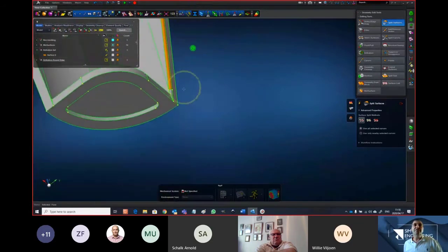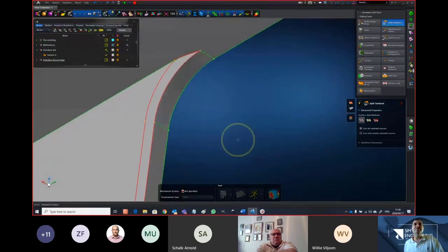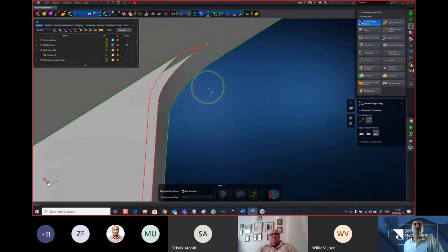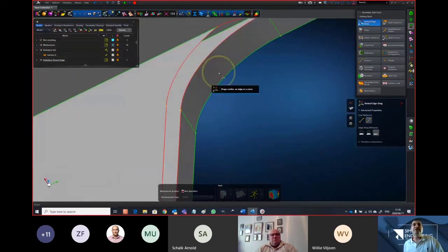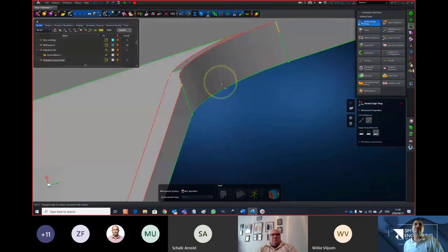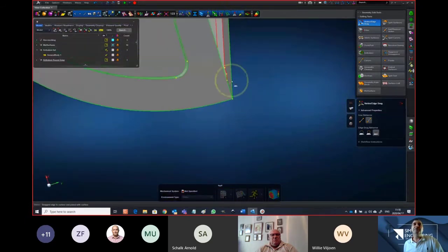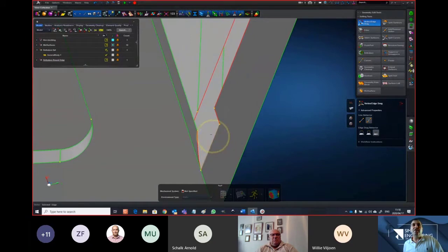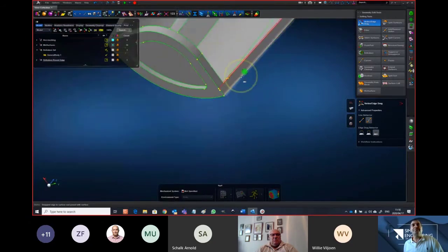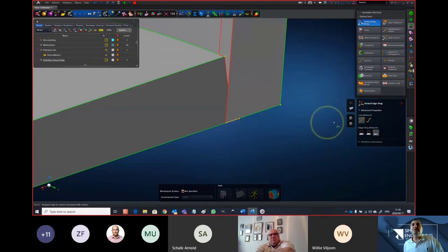Right, so I'll delete these two faces as well as a way to get rid of that feature because the defeaturing feature failed. And now I'll have access to all my sheet and surface feature tools, like for instance the ability to drag this edge to match up to the extension of that face over there. And now I just have to do this for these three edges, and then just take care of what is happening on the sides here before filling it in and recreating a solid again. So now I'll just switch to straight edges and I'll pull this edge that's curved over there into this location over there.